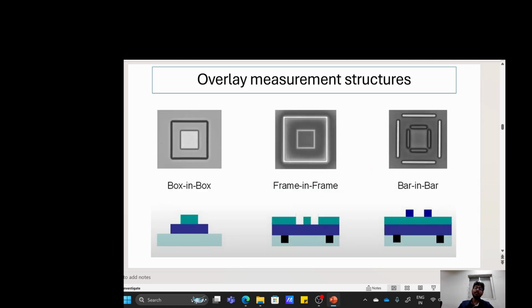Okay, now there are some alignment marks. For the lower feature sizes, let us say 2 micron features, you cannot put the alignment marks of higher features, like 50-60 micrometer features, because you cannot align the 2 micron features with the 50-60 micron alignment marks.